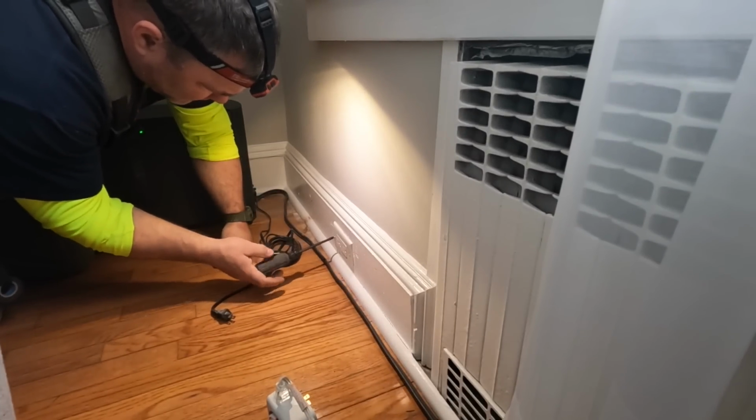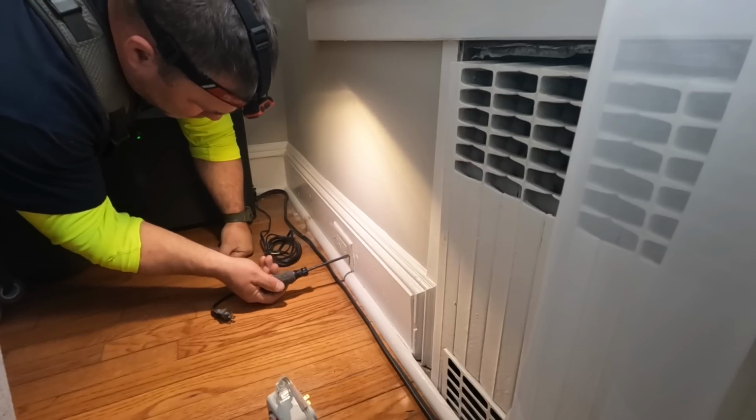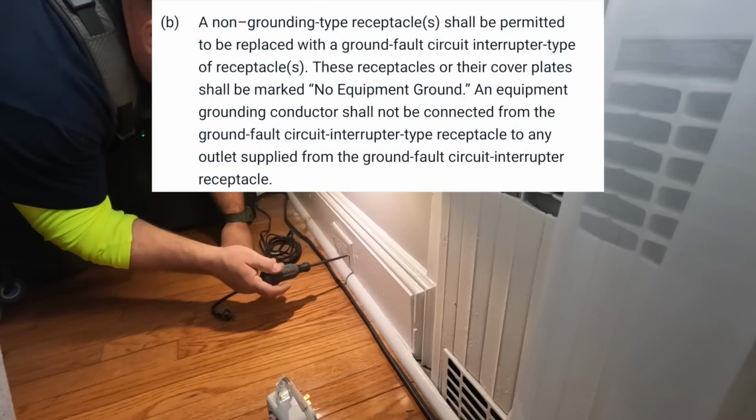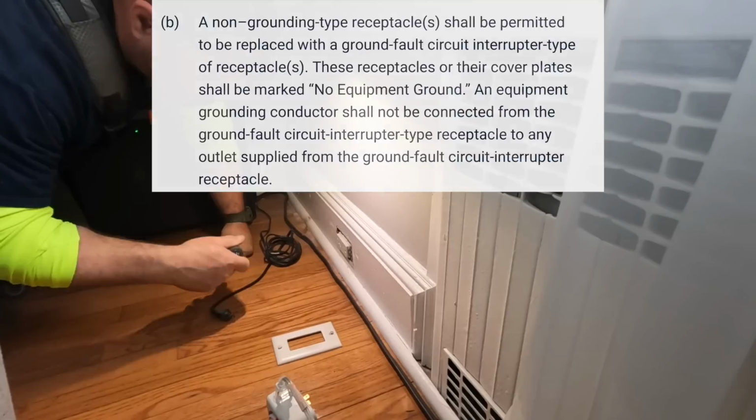This one's actually pretty nice. It's got a GFCI receptacle here, which is the code for when you replace receptacles connected to knob and tube circuits. You just have to put no equipment ground sticker on the plate right there to be compliant.